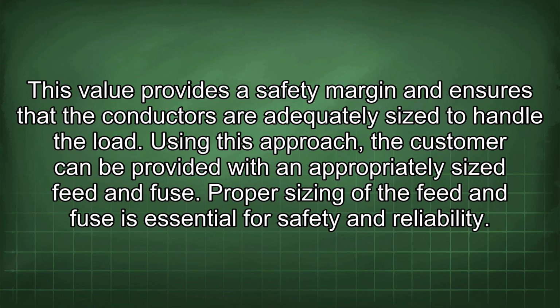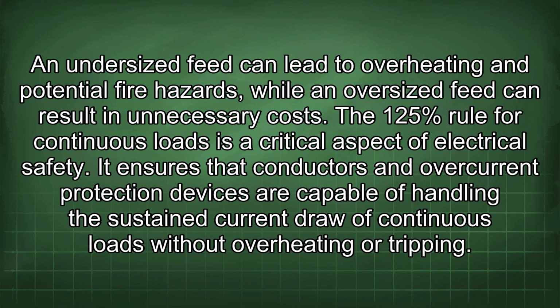Using this approach, the customer can be provided with an appropriately sized feed and fuse. Proper sizing of the feed and fuse is essential for safety and reliability. An undersized feed can lead to overheating and potential fire hazards, while an oversized feed can result in unnecessary costs.